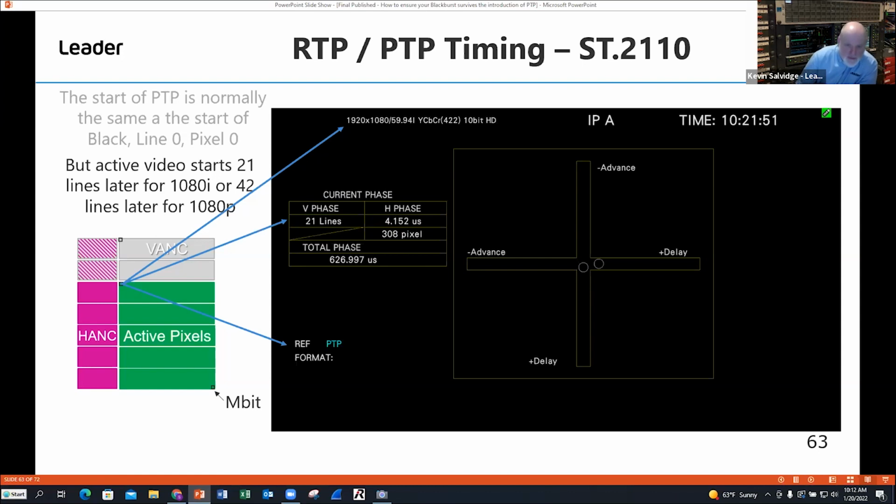One more question I'd like to throw out there, Steve. What is the security method used for PTP so it isn't vulnerable to something like a DNS attack? Well, normally your PTP network is completely isolated, never hits the world. It never is anything within your engineering network. PTP is normally a confined network in and of itself, and it doesn't leave your facility. So an attack of the PTP network itself is not easy.